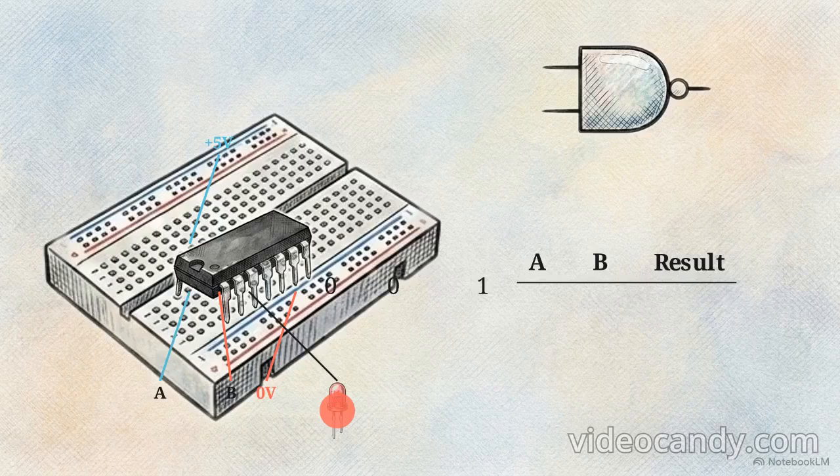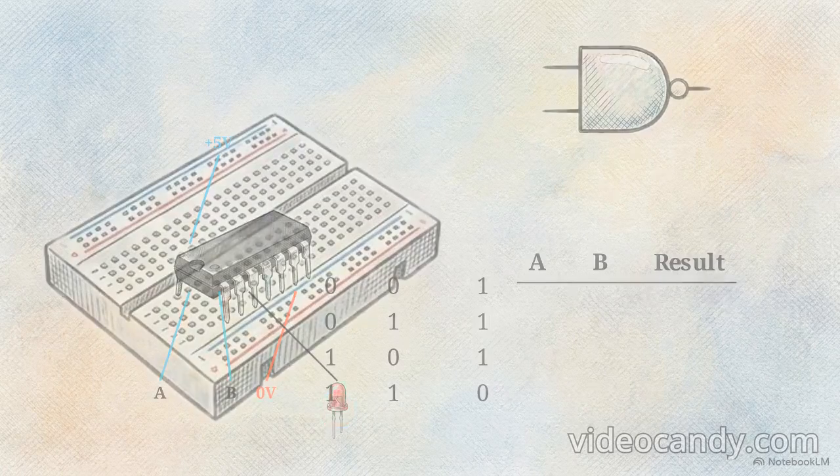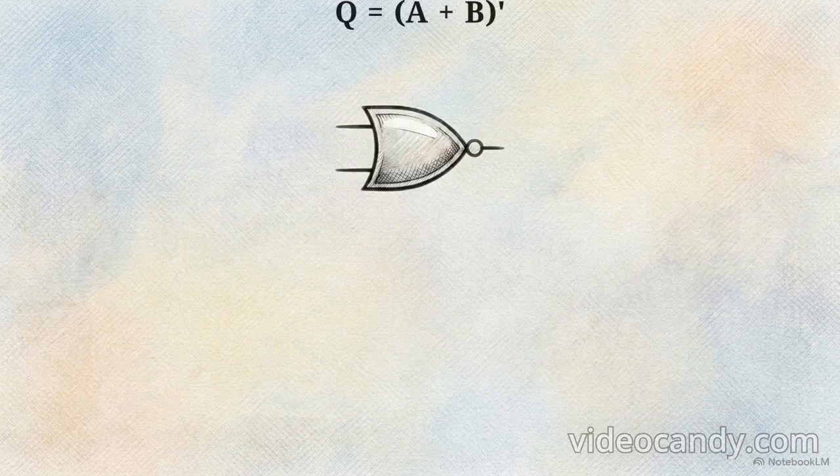If we introduce a mixed state, 5 volts to pin A and 0 to pin B, or vice versa, we still lack consensus. The output remains high and the LED stays active. The state only flips under the final condition. By driving 5 volts into both input pins, we trigger the NAND rule. The gate output drops to 0 volts. The logic goes low and the LED shuts off.